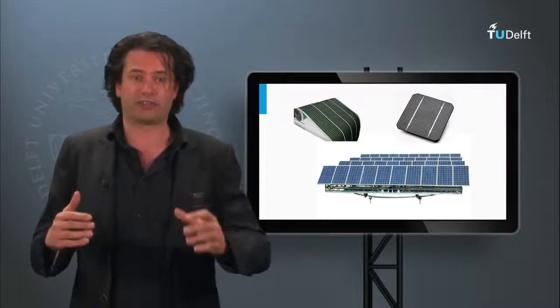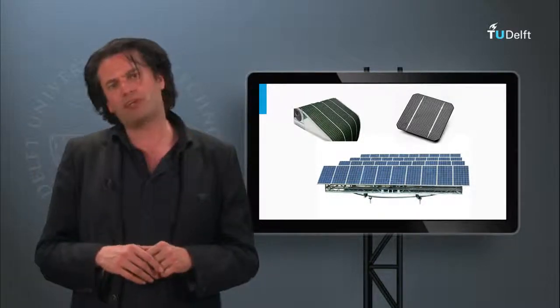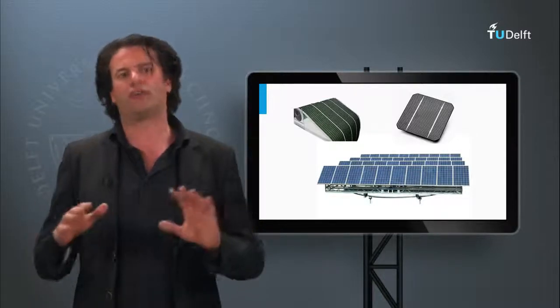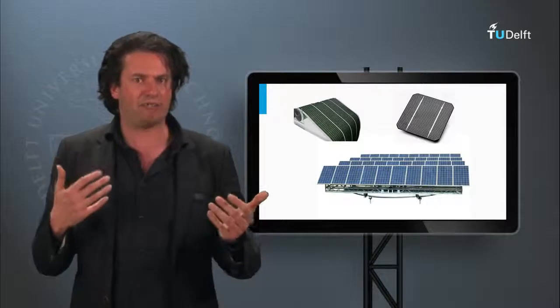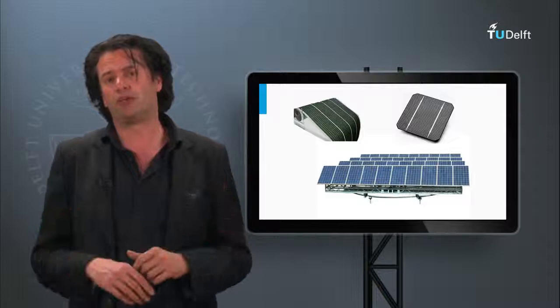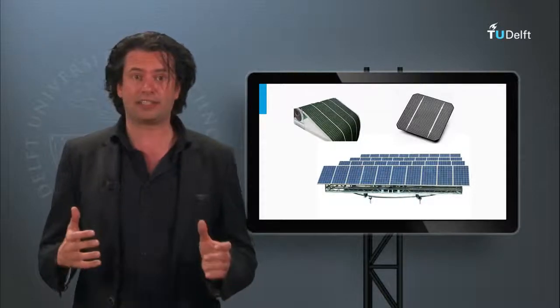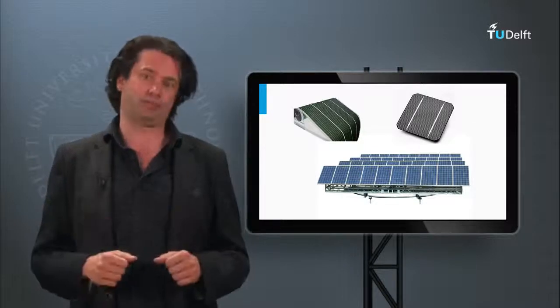But conventional crystalline silicon modules are also very bulky. Polycrystalline silicon modules cover a lot of area. Monocrystalline modules are more area efficient but are more expensive. Amorphous silicon modules are cheaper, lighter, and sometimes even flexible, but give poorer yields.